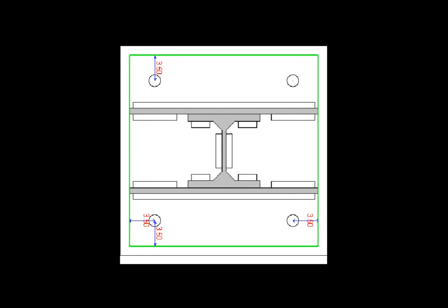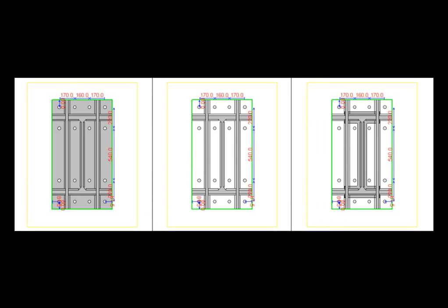When stiffening plates are present, the surface of the applied load footprint is not just that of the member's transverse section. It includes the contact surfaces of the stiffening plates as well. The figure shows two long stiffening plates connecting the column to the base plate. The adjacent white rectangles represent the welds. These issues must be considered when we define the bearing surface. The designer is responsible for specifying a realistic bearing surface.